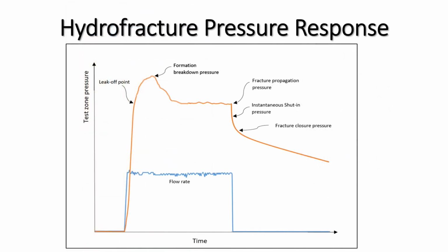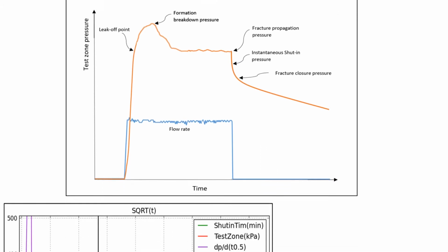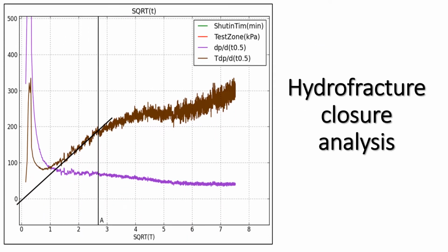The measurement of rock stress through hydrofracture requires sealing a section of the hole and pressurizing it until a fracture is created in the borehole wall, then propagates. Fluid injection is then stopped and pressure decline takes place and the fracture closes. The process is normally repeated by pumping again and reopening the fracture.